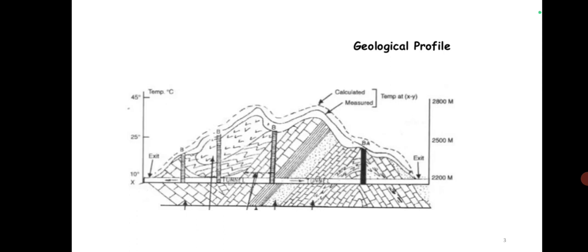Whereas if soft rock is found, like shale, which is friable, that is, easy to break, poorly compacted sandstone, chalk, then porous varieties of limestone and dolomite. Limestone and dolomite, if they are without any pores, are very hard and compact, and then they are consolidated rocks. But if they are porous, that is why we stressed that in the detailed survey we have to check the porosity, permeability, and modulus of elasticity of the rocks.